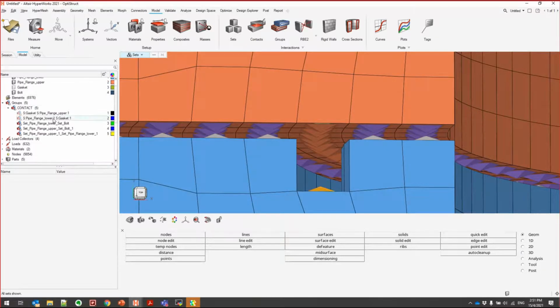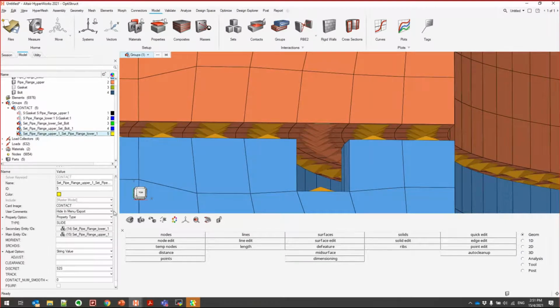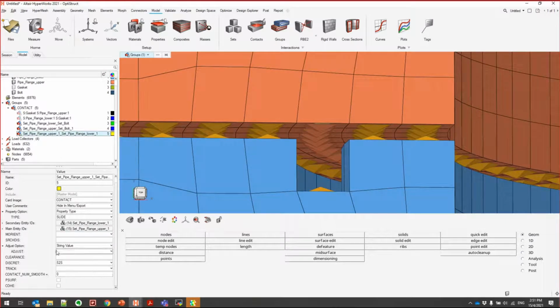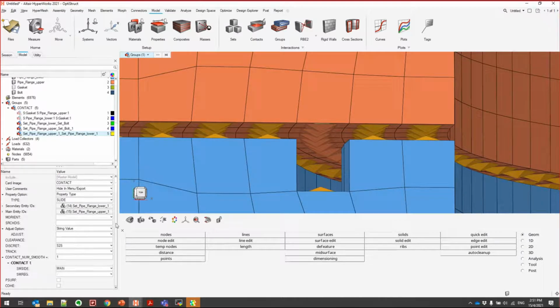So that's why in the contact you have this option here. First is the side, whether you want to smooth on which side. Let's say if you smooth both master and slave, top and bottom, then you need to choose the region as well. You can either choose all the region, which means both regions here will be smoothed, or you can select another set where only one region is smoothed.